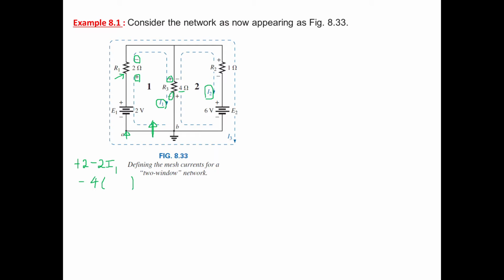So first find the direction of the current I1. I1 is flowing from top to bottom, so it is positive to negative, so we write I1. And the next current flowing, I2, is also flowing, but in the opposite direction, from bottom to top. So we have to subtract these 2 currents and write. So the current flowing in resistor R3 is I1 minus I2.